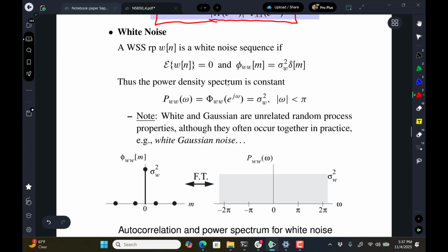And my manager helped me a lot because he said, don't get very sophisticated in your filter because we don't have much processing power in the FPGA to dedicate towards this filter design. So it was a cascade of moving average filters. It was something that was pretty simple to implement in the FPGA, not an elaborate high-order Butterworth or Chebyshev or Bessel filter or something.